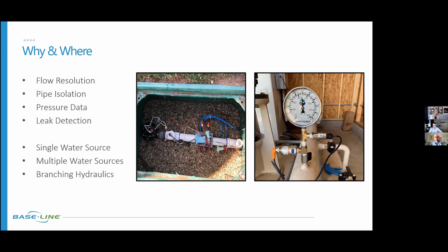And then the client added the baseline pressure transducer to that same setup so that the controller has visibility of the pressure as well. And at this particular site, there were multiple water sources that they were prioritizing, one coming out of a pond, one coming out of a well. And so they were able to retrofit in the pressure transducers to capture that data coming out. Yeah, you make an excellent point. Being able to get that data at the controller rather than just having the pump station itself separated and isolated from the control system is awesome.